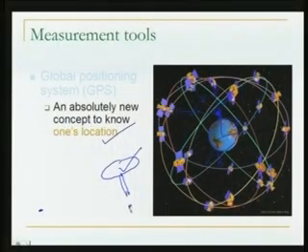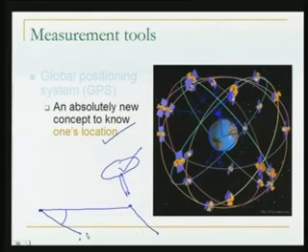Now what you can do? If you know all the coordinates, latitude, longitude and altitude, of 2 points on the surface of the earth, you can measure the distance between the 2 points. If you know the lat, long and altitude of a third point also, you can also measure the angles. Well, with some more points, you can find the area.